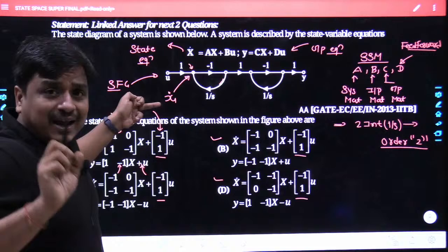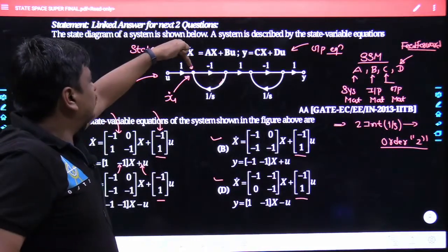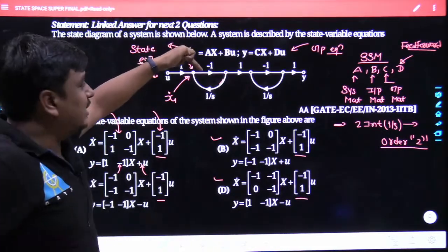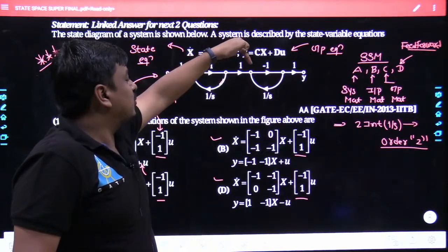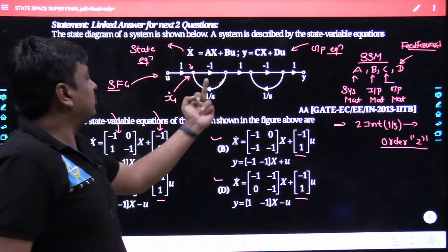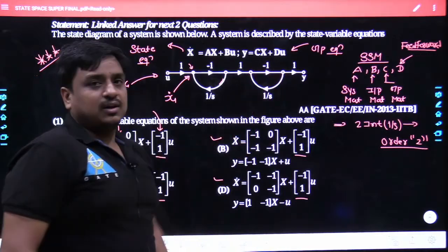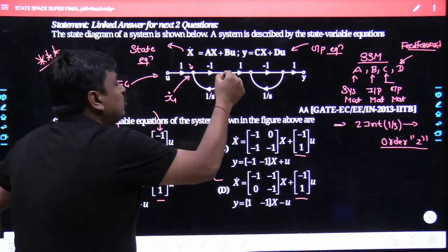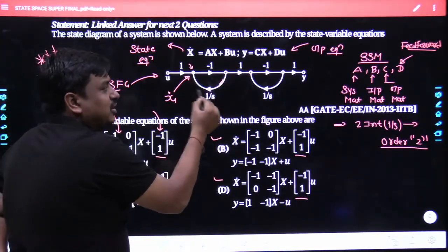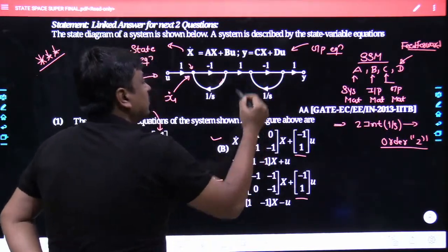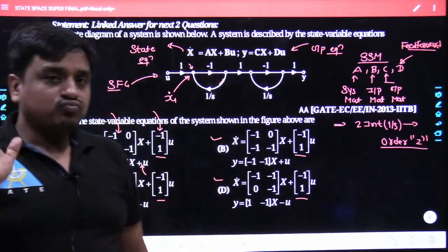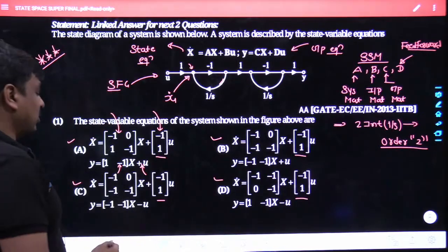So nobody should think that I should be taking x1 dot or x2 dot over here, and the same process goes with this. Yes, I should not be feeding x1 or x2 dot over here or here. I should feed x1 or x2 dot over here or here. And now what will happen? Now there would be an integration in time domain because of the factor of 1 upon s, and similarly there would be an integration in time domain because of the factor 1 upon s. Agreed? Till this point, nobody should have any doubt as such.